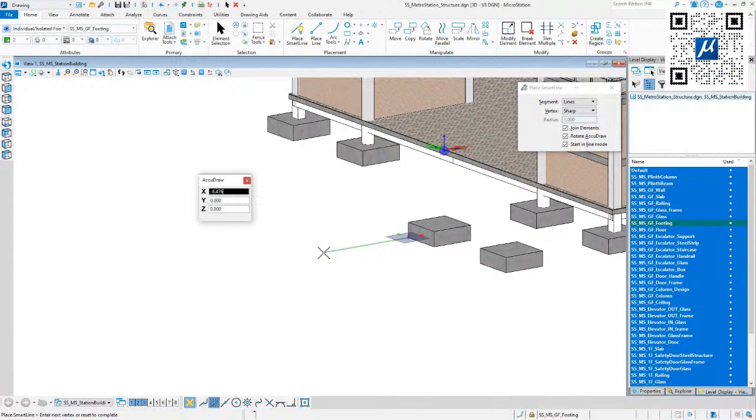And then I type the distance. Let's go 7 meters. Type 7. I don't have to type minus and plus and whatever. Accudraw knows what I want to do. And that's what I mean if I say it's so easy to work with. Look at the screen, move your cursor in the right direction, type how far you want to go.